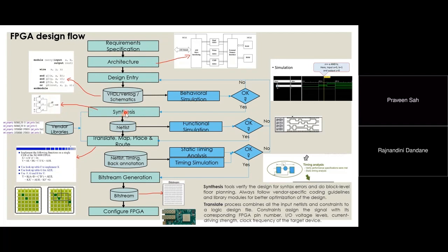Now, once you have this netlist, you do the functional simulations. Now you must be asking what is the difference between these behavior simulations and functional simulation. Okay, let me tell you. This behavior simulation is nothing but you are just simulating the RTL code.